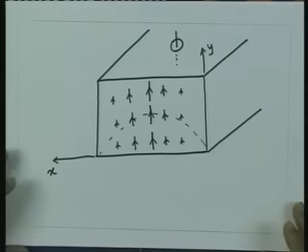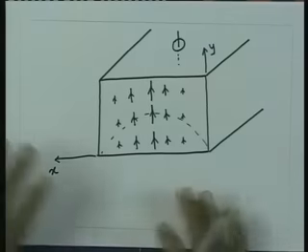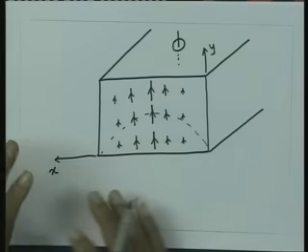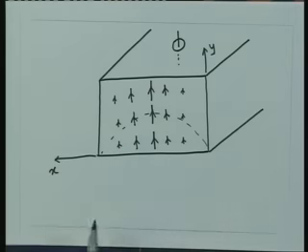So in practice, whenever we do the experiment or we carry high frequency signals like microwave signals, these signals are carried by a rectangular waveguide, and this rectangular waveguide always operates in the dominant mode, which is the TE10 mode.